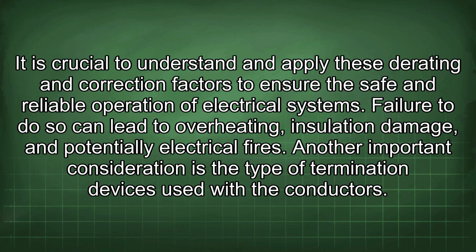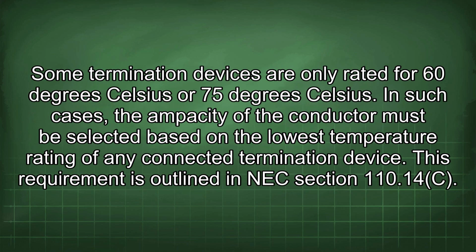Another important consideration is the type of termination devices used with the conductors. Some termination devices are only rated for 60 degrees Celsius or 75 degrees Celsius. In such cases, the ampacity of the conductor must be selected based on the lowest temperature rating of any connected termination device. This requirement is outlined in NEC section 110.14(C).